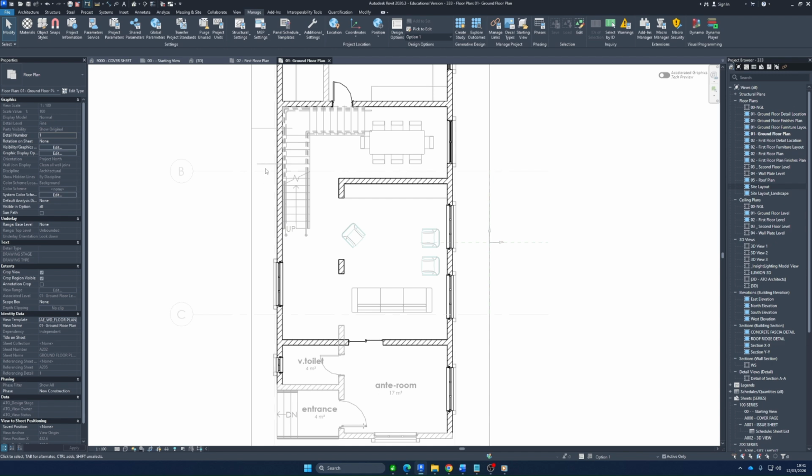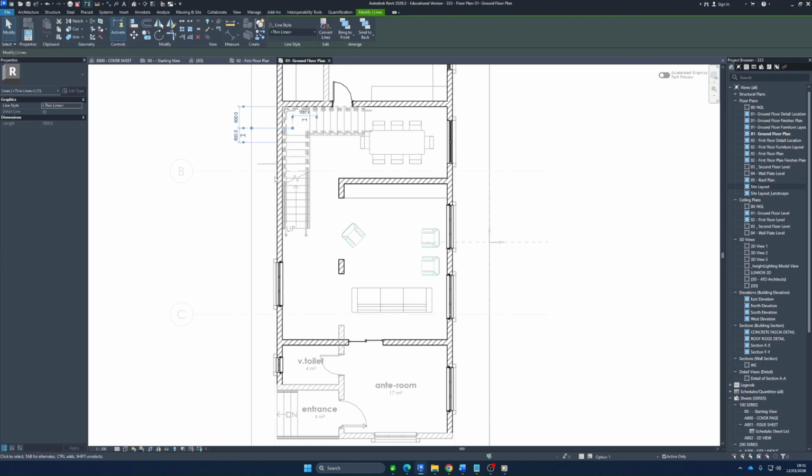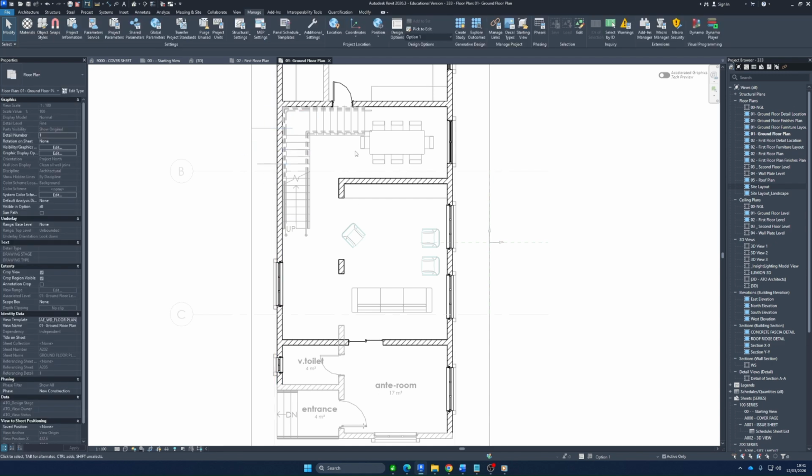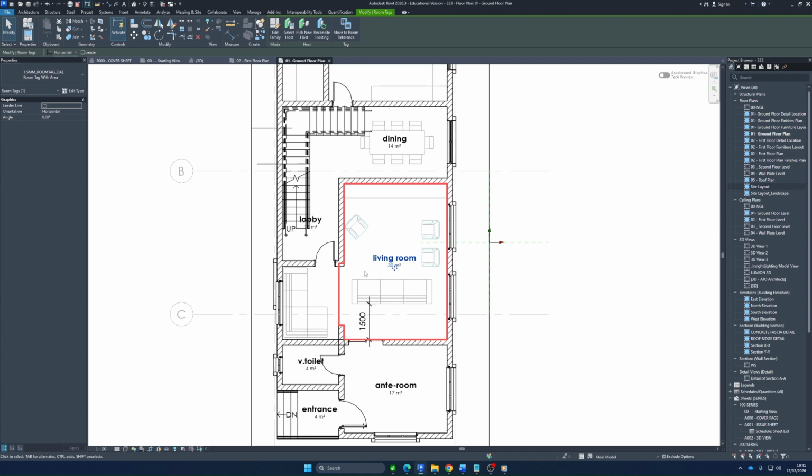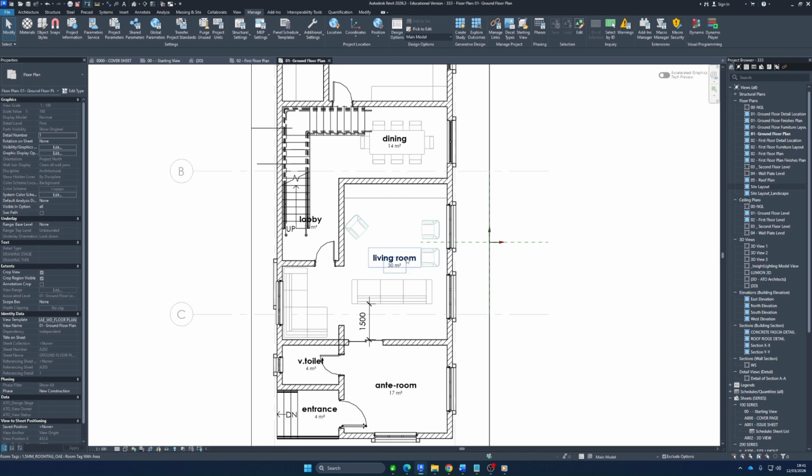So whatever 2D element you delete affects the entire view. All right, it affects the entire view. So we must have that in mind. So we're only adding 3D elements. Like we can see, even the rooms are 3D elements, so we can add rooms. And we'll discuss using design option rooms in more detail later.